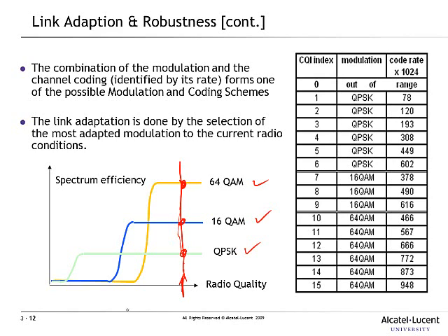Okay. Now, if the radio link quality were to drop to somewhere here, again, if I were to draw a vertical line, you can see that 16 QAM has the best performance. So when the radio quality is average, you might use 16 QAM.